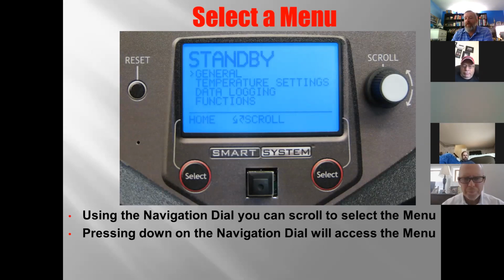If we have extra parameters now, that's okay. The other one just didn't get it. We just added more to it. What's important though is I can connect a boiler from 2005 and a boiler from 2020 together, and they will run and communicate with each other. Just always make the new boiler the lead boiler.